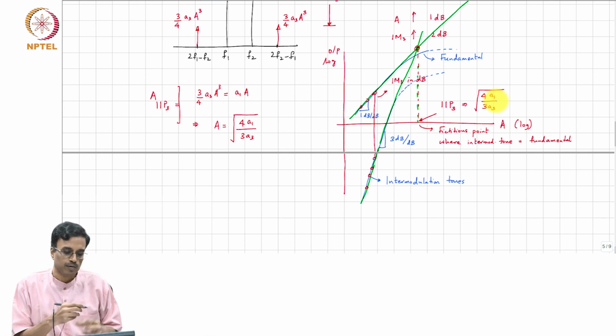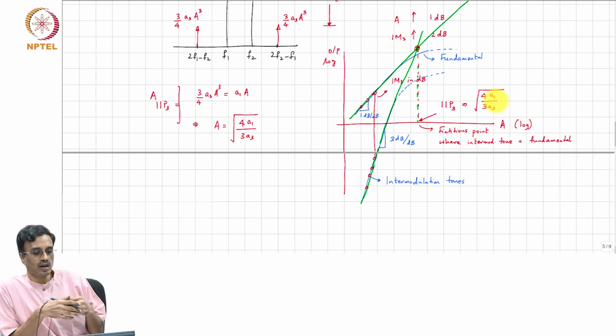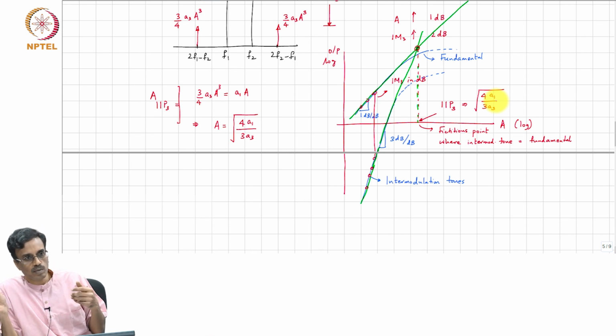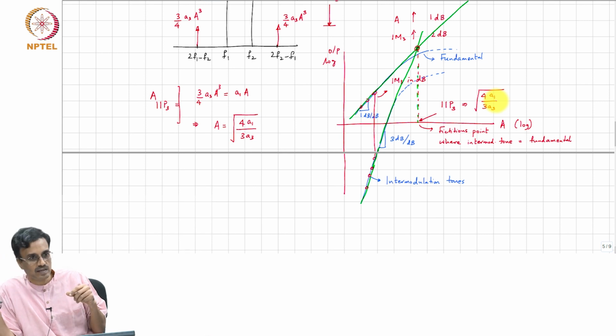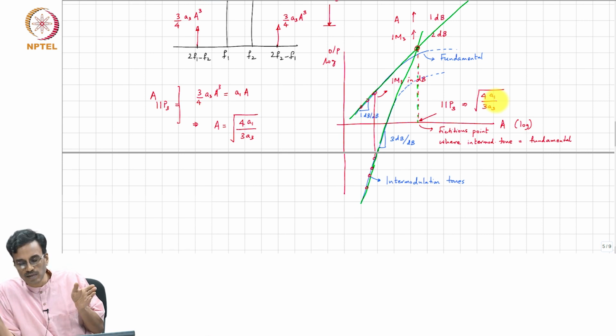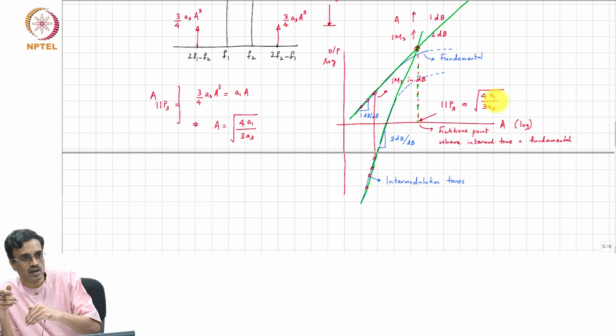If an amplifier is producing a third harmonic, the fundamental and the third harmonic go through the same physical path, but that path may have some frequency dependence. So the higher order harmonic may get attenuated by the time it goes into your measurement instrument, right.